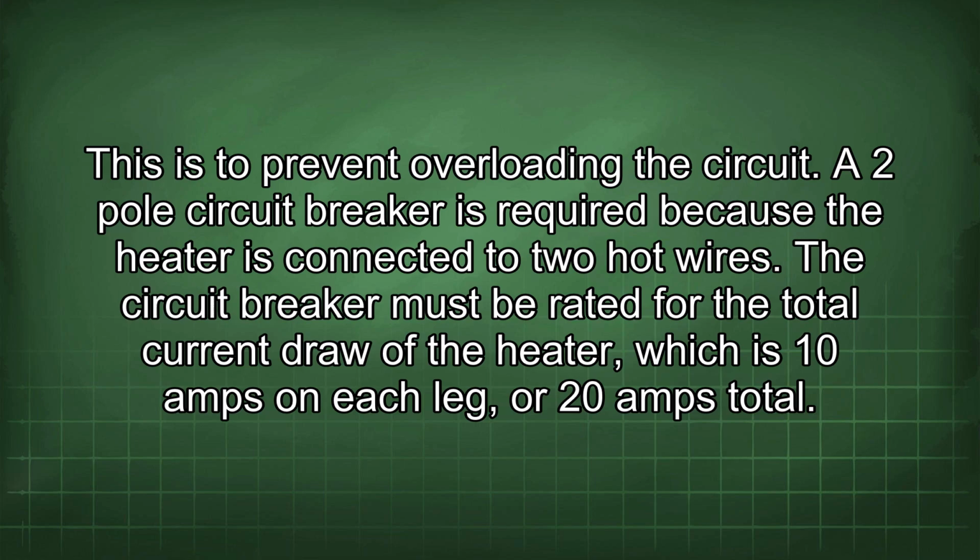A two-pole circuit breaker is required because the heater is connected to two hot wires. The circuit breaker must be rated for the total current draw of the heater, which is 10 amps on each leg, or 20 amps total.